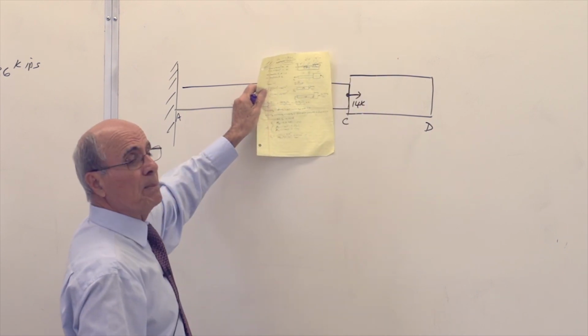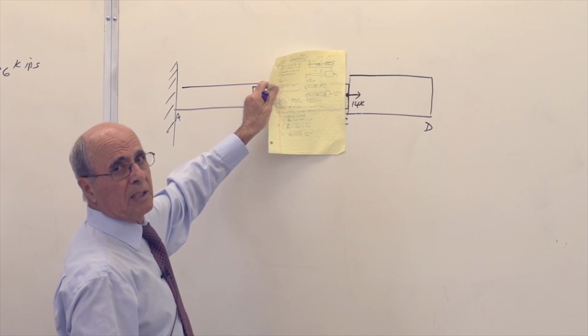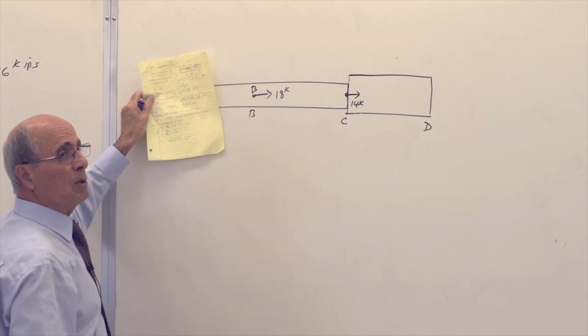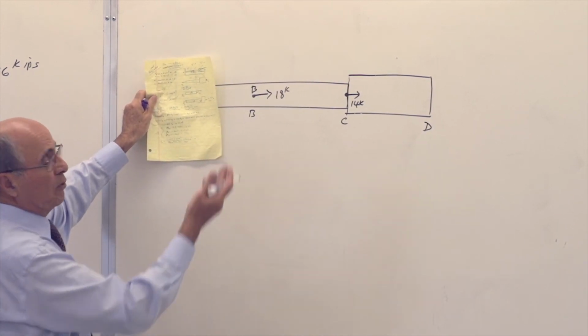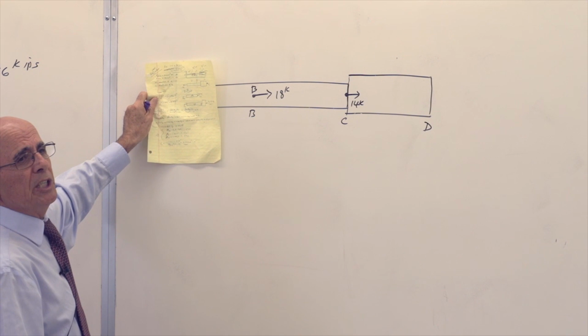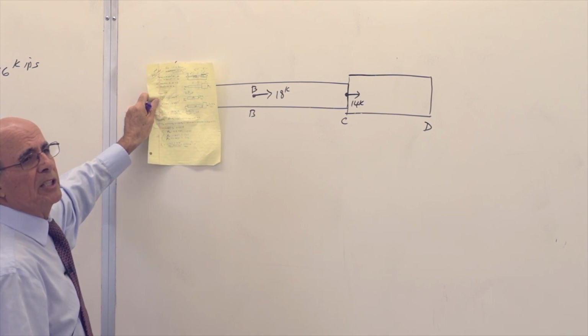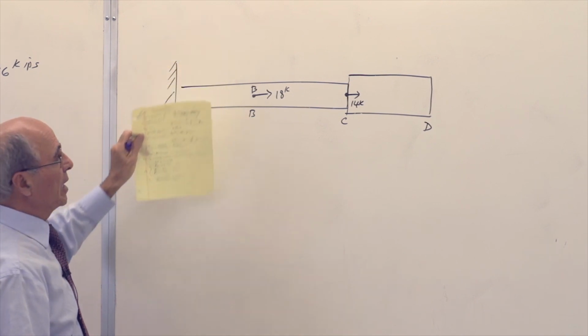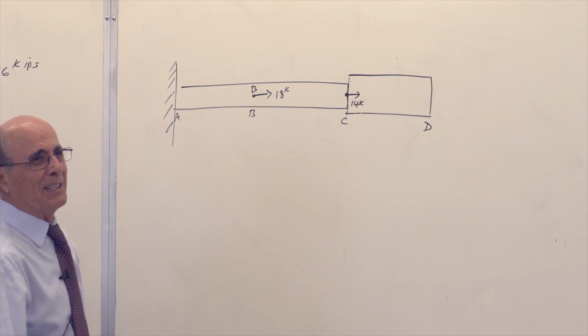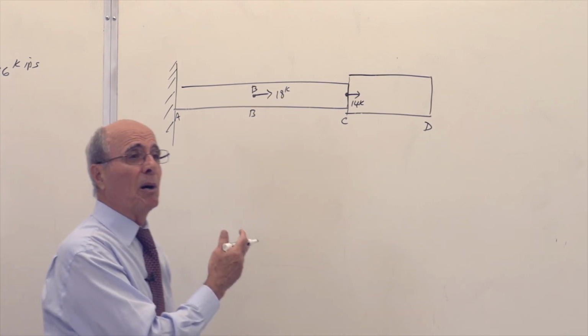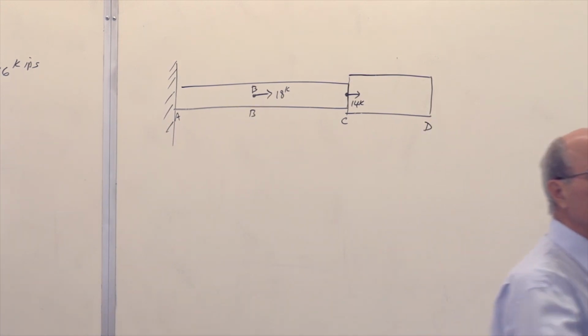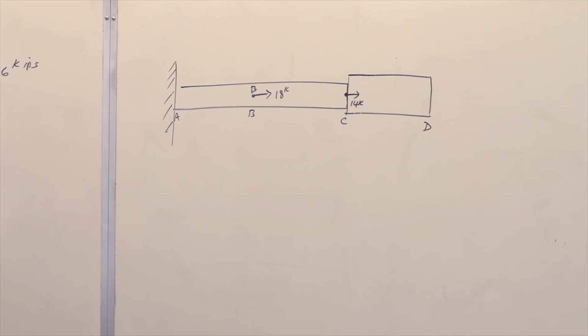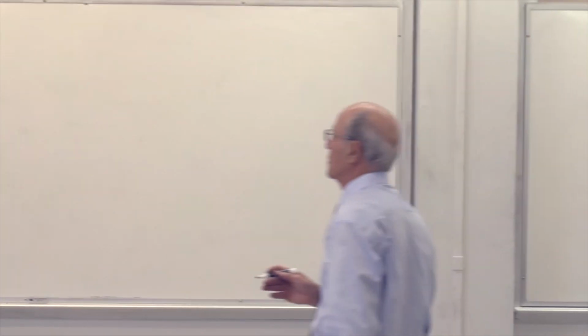The force in this member would be 14, tension. The force in this member would be both of them on one side. Both of them will be 32 in tension. Everybody understand that? Yes? Okay, but that's not the problem, unfortunately. Because if this was the case, this problem will be determinate because you can calculate the delta. Yes or no? The problem is this.